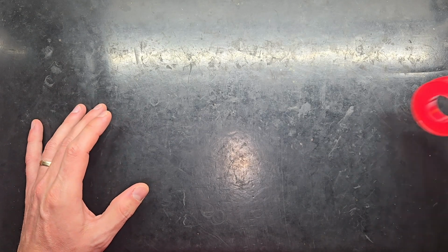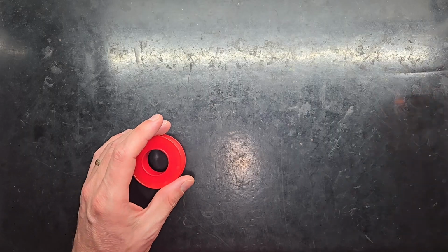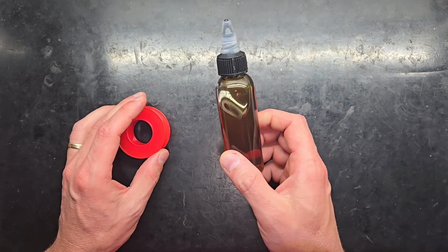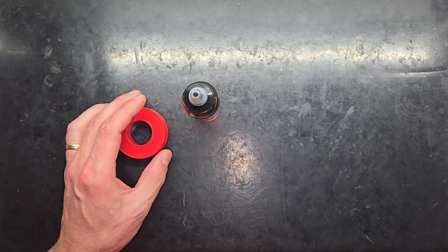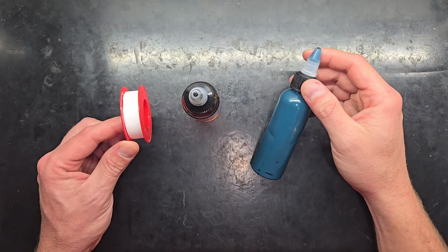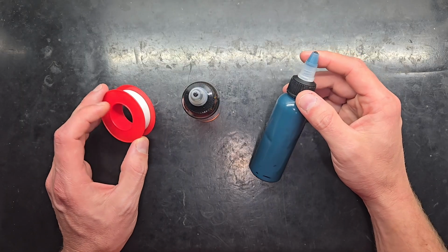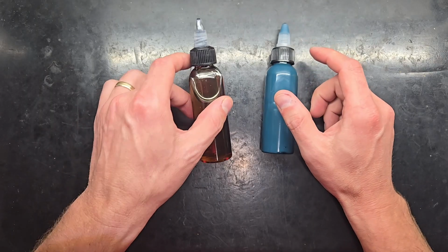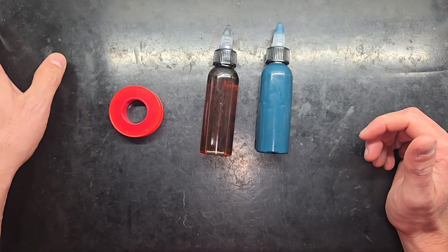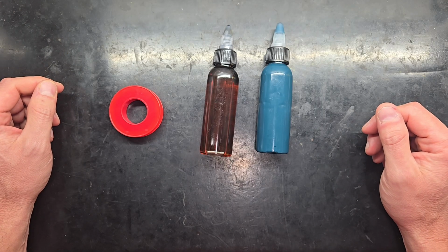The next thing we're going to talk about is the meat and potatoes, and that's going to be lubrication. So for lubrication, we have many types. Most of you are going to be familiar with our liquid lubricants. We then have our grease lubricants. We also have solid lubricants like Teflon. And then there's a fourth one that's often forgotten about, and that's actually air. There are bearings in industrial machines that are supported by air. So it too can act as a lubricant.